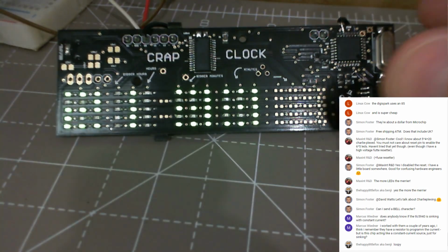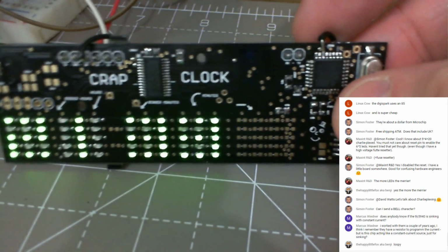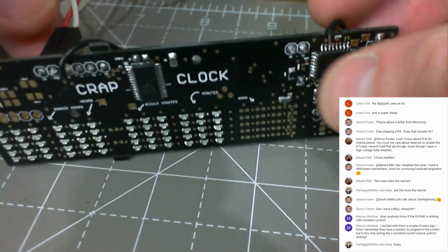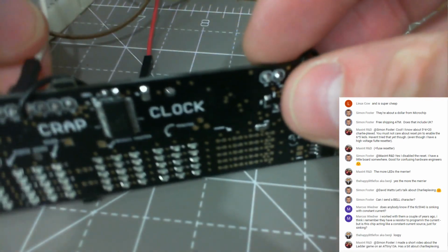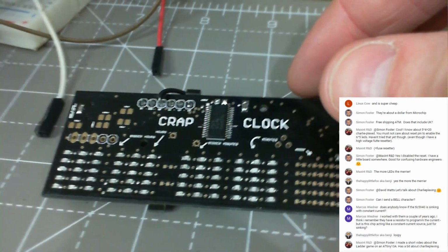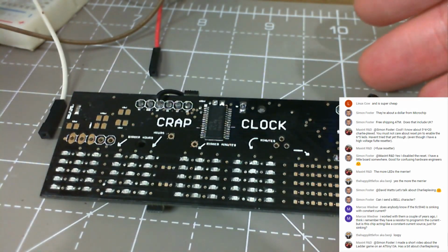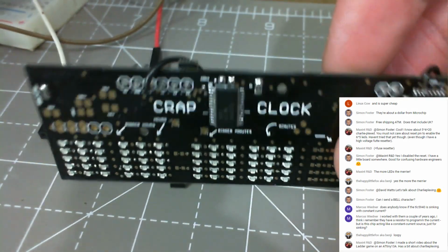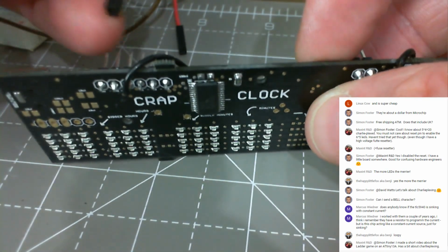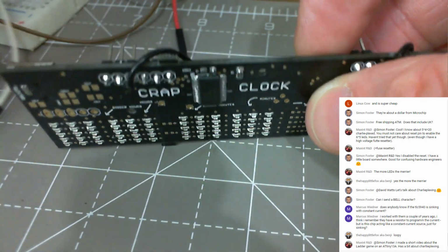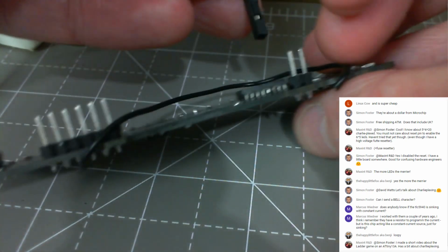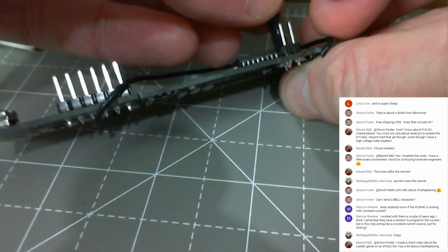So let's plug in the programmer stuff, and we'll be able to just program it for the correct time. Oops, daisy. Let's just unplug everything, and we'll plug in our programmer. The programmer in this case is an Arduino Uno. So we want ground in first. Actually, we'll do ground in last. And that is our reset pin. So put reset in there.